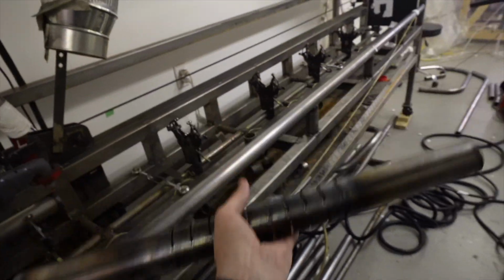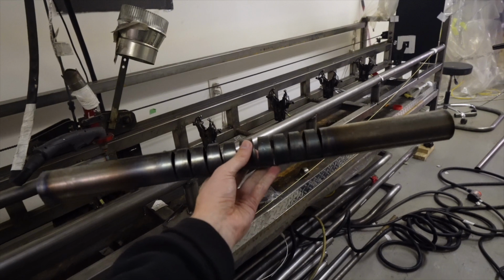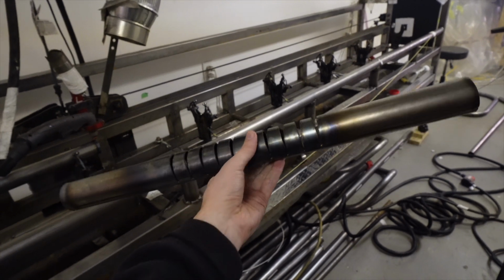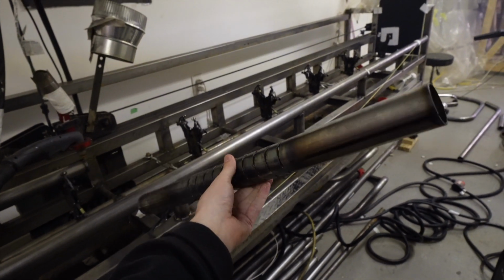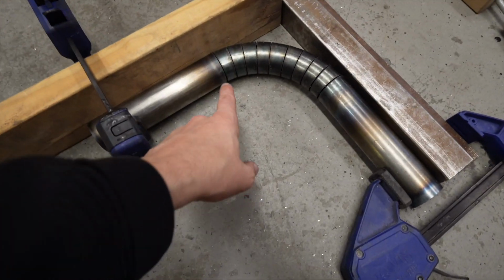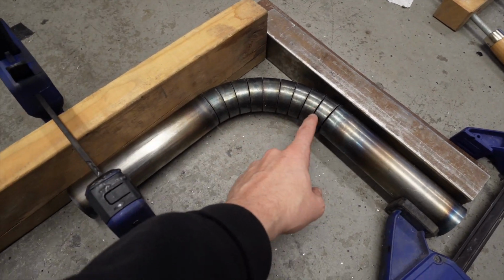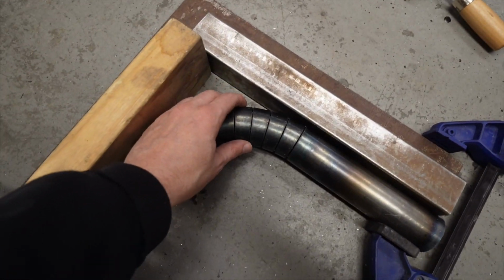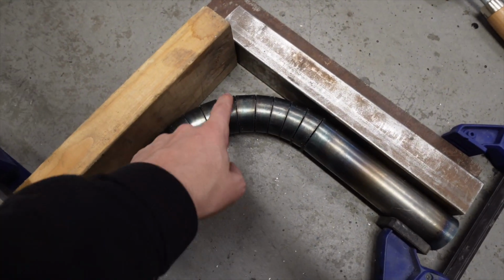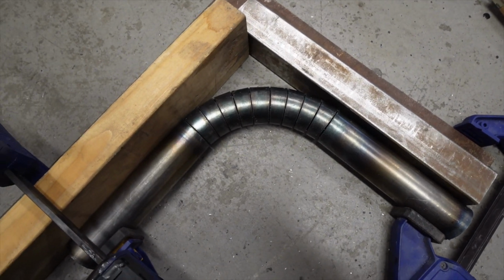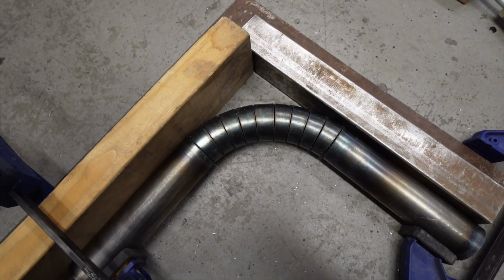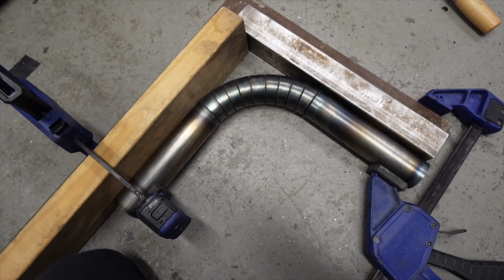But we'll bend this up. I'll put it in a small jig, put some tacks in and just see if we get 90 degrees, if the ends are the correct length. And then if that works, then we should be able to make some bigger tests. Just before I tack, there is a gap between each of the slots that's going to be difficult to avoid as long as one part is connected on the outer edge. There's always going to be a gap, so I'll think about that. I don't know if that's going to be an issue for welding, but we'll tack this up and then we'll see.